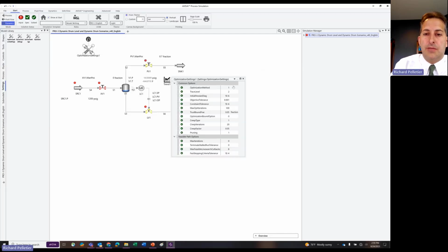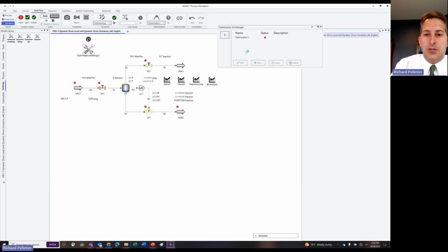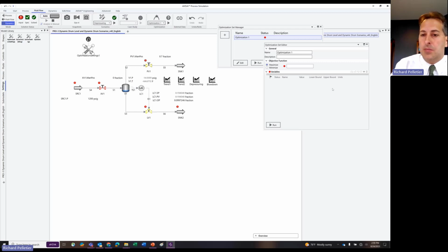This would be the closest thing available to you to putting in, say, a step size limit. Otherwise, the only limit in the optimization is the bounds themselves. So whatever bounds you end up putting on here, that's just the limit, but it's not changing how big or small of a step size it takes from one change to the next.